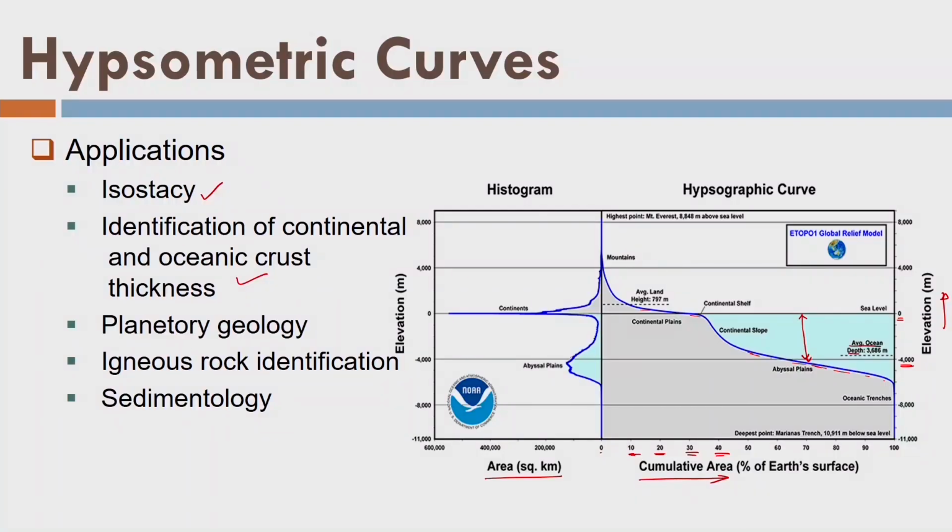With this we say that we are now close to the end of our lecture 1 on introduction and the fundamental concepts of hydrographic survey. I hope that you could understand why we do the hydrographic survey, what tides are, what low tide and high tide are, what the frequency of the tide is, how tide varies, and how the attractive forces accumulate the water on one point on the surface of earth, creating the high tides and low tides. With this we realize how hydrographic surveys are very important for river as well as for the sea.